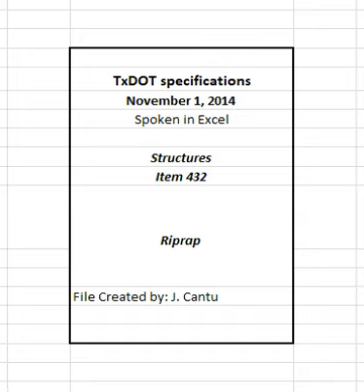Payment for excavation of toe wall trenches, for all necessary excavation below natural ground or bottom of excavated channel, and for shaping of slopes for riprap will be included in the unit price bid per cubic yard of riprap.